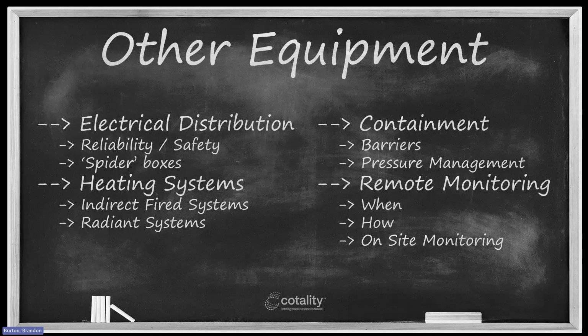Number one, I would highly, highly encourage that with fired systems, they be indirect. I highly discourage the use of direct fired heating systems for a drying environment for lots of different reasons. One, because they add moisture to the environment to a degree. We can argue about how much, but they add moisture. Secondarily, if those systems are not properly balanced, they are going to add a lot of carbon monoxide to the environment potentially if we don't have complete and total combustion. So there are a couple of red flags associated with those.